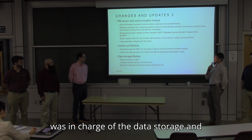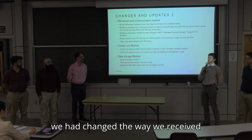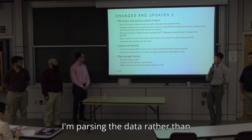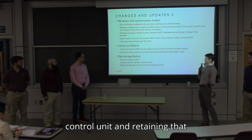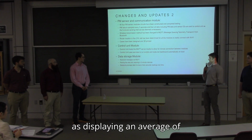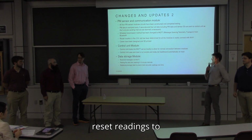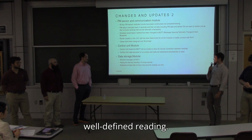So I was in charge of the data storage and data display, and as they spoke, we had to change the way we receive messages into the dashboard. So obviously they said MQTT, as well as now, from last time we spoke, I'm parsing the data rather than receiving the data parsed from the main control unit, and retaining that information in 5-minute intervals and storing it into a database, as well as displaying an average of the data rather than the 5-second reset readings to ensure a more accurate, well-defined reading.